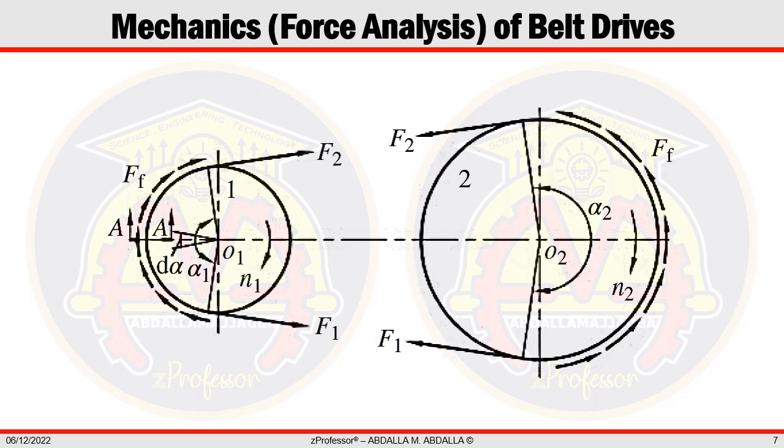The belt is first mounted by loosely surrounding two pulleys with a smaller center distance. Then the two pulleys are separated to the chosen center distance. As a result, the belt has an initial tension of F0 and clamps securely on the pulley surface. Since it guarantees the belt will function effectively under design loads, the initial tension is crucial. At the point where the belt and the pulleys meet, normal force N is generated in the radial direction as a result of the initial tension F0.